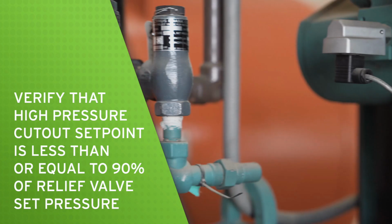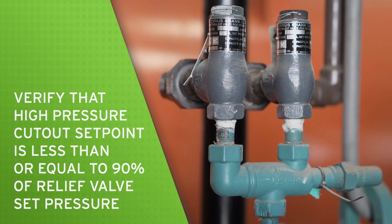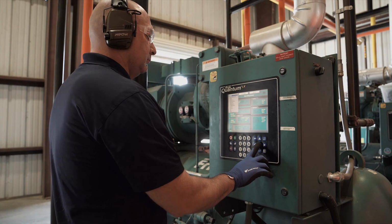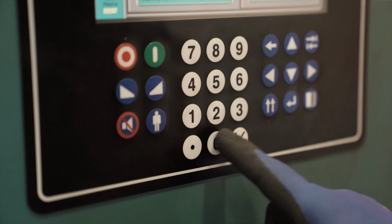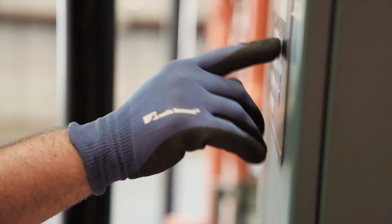taking place. Once approved, verify that the high-pressure cutout set point does not exceed 90% of the compressor relief valve set pressure. For example, if the relief valve set pressure is 250 psi, the cutout set point must be less than or equal to 225 psi. Using the set point reduction method requires changing the set point to within the compressor's normal discharge pressure range. Once the set point has been adjusted, the compressor will de-energize, thus concluding the test. After completing the test, the alarms can be cleared and the compressor restarted.